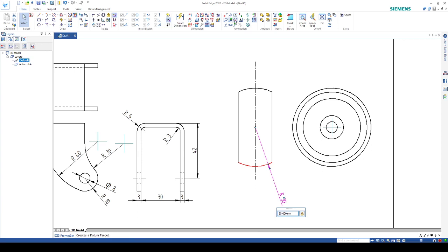If not, I'll just type it in text and I'll remove this. It's S30, 60 because it's diameter. A spherical diameter of 60 mil is what you're looking for. Instead of radius 60 or radius 30, it's S60, S for sphere.